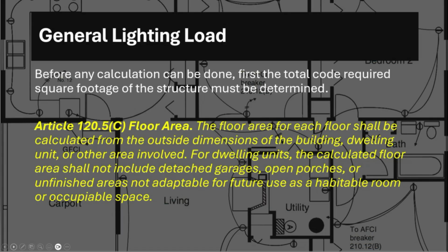So I interpret that as, if I have a crawl space, well, of course, that's not a habitable area. If I have a completely unfinished basement, nothing but concrete walls, that area could be finished off into a habitable space at a later time. So when calculating these, the way I see this and read that description, I would include that square footage also when calculating this load.